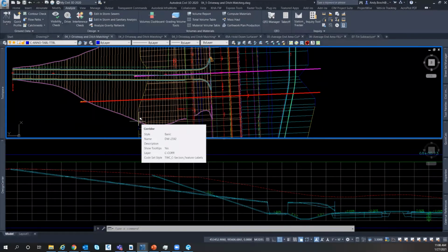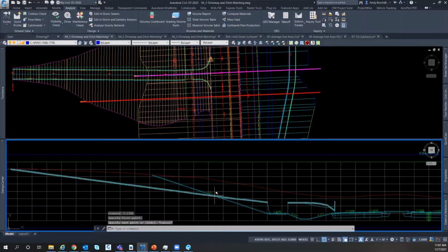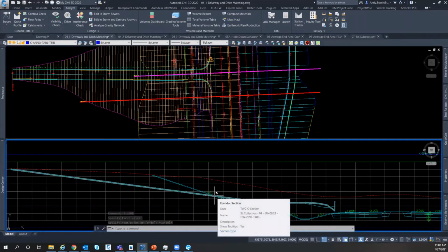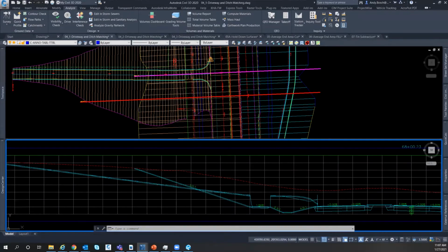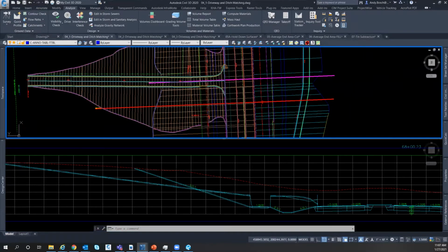My CAD just froze up a little bit there. What we'd really have is a nice line running from this point here to a point right here where I'm tying into our trail, and this is our intersecting point. As well as figuring out our ditch grades, we'd want to target that proposed surface off of the roadway. So I'm going to switch drawings here.